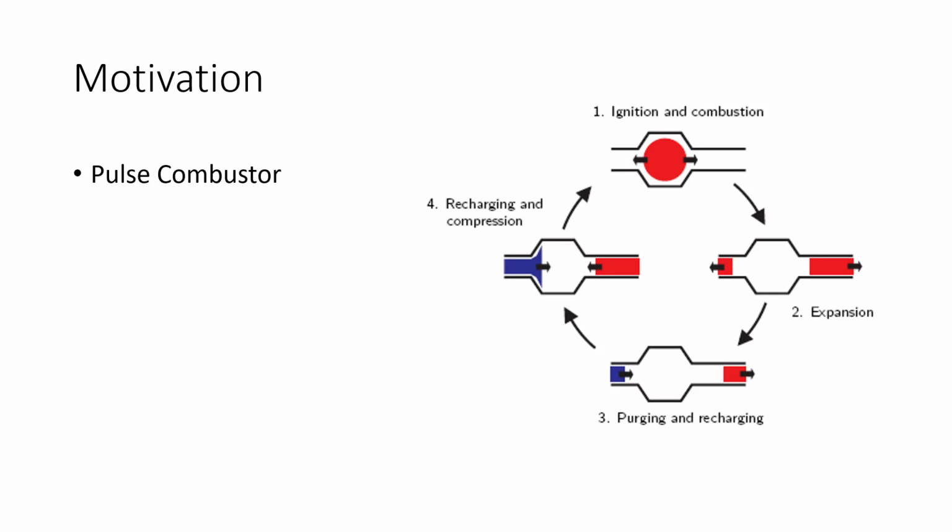Now, you all may want to know, why should we care? Well, what we will see during this lab in the rocket tube is exactly what happens in a pulse jet engine, which, as the name implies, works by injecting fuel into the combustion chamber in pulses rather than in one stream. These types of combustors are more efficient than steady combustors and have increased combustion intensity.